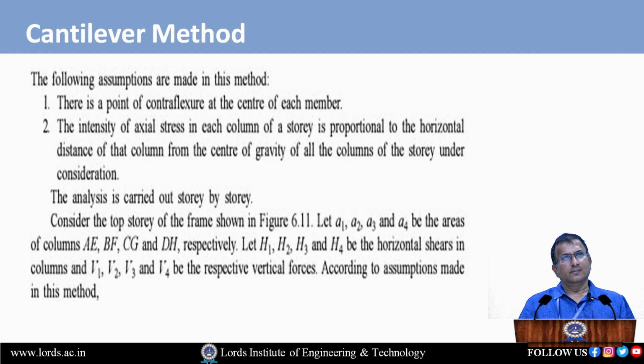For analysis of the frame, we should concentrate mainly on two assumptions, because the total analysis is based on these two assumptions. The first one is that the point of contraflexure, or point of inflection, or virtual hinge, will occur exactly at the center of each member. You have already read at UG level what the point of contraflexure is. It is also known as the point of inflection, and the third name for it is the virtual hinge. It is a point where the bending moment changes its sign, or bending moment equals 0.